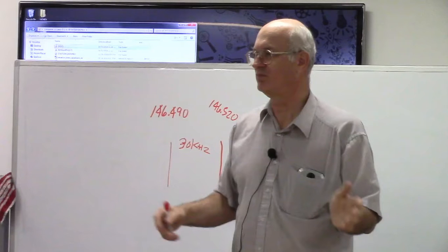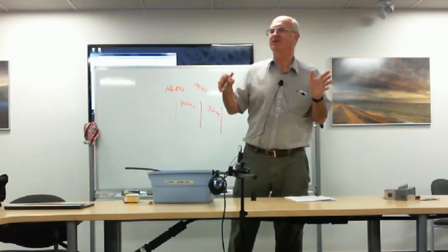But at 2 meters, when you're tuned to 5.8, the rest of your receiver is still pretty wide. You can basically pick up the whole band. But at the last stage, you put your filtering in and say that's this channel, that channel, this channel. But it could still get into your set and start mixing if it's close enough.